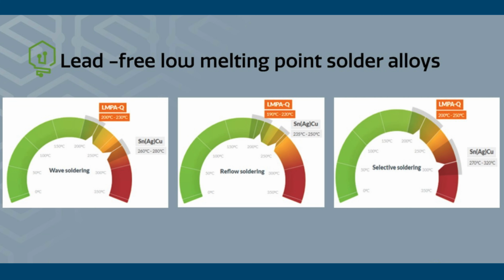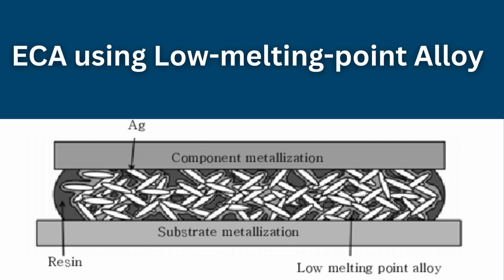These fillers consist of two metallic components: a low melting point alloy powder, e.g., SnPb or SnIn, and a high melting point metal powder, commonly copper. During curing, the low melting alloy melts and dissolves part of the high melting metal. The liquid phase then forms a new alloy that solidifies rapidly, creating metallurgical connections between particles. This process forms electrically conductive pathways while the polymer matrix provides adhesion.